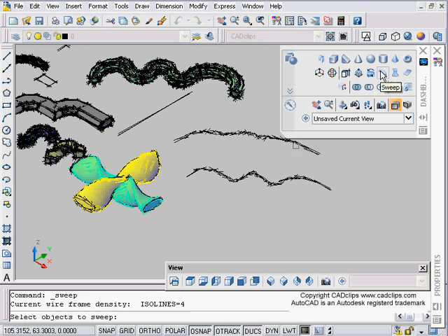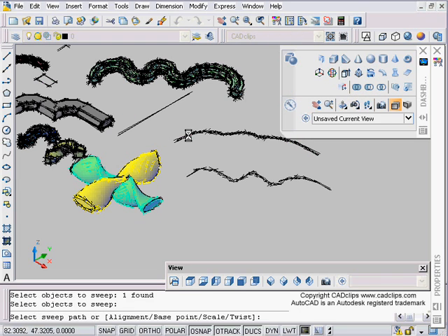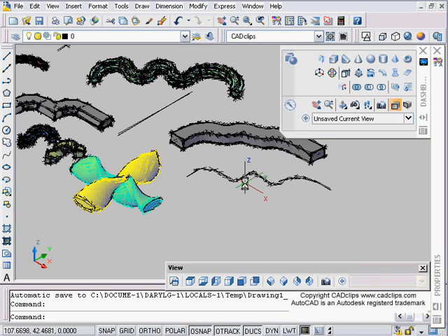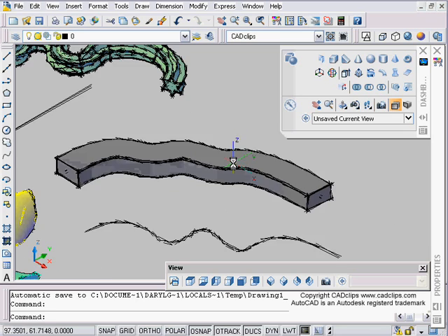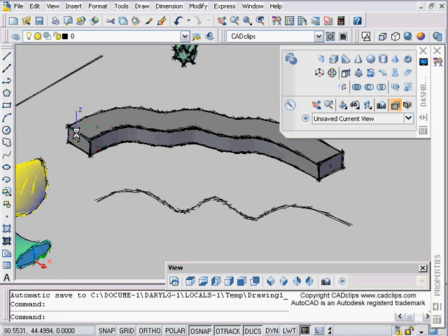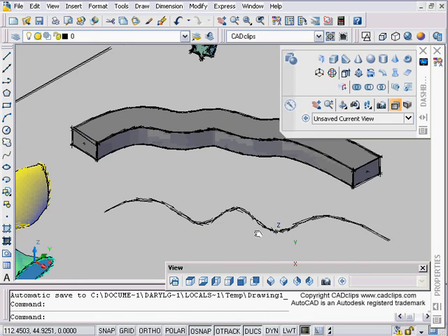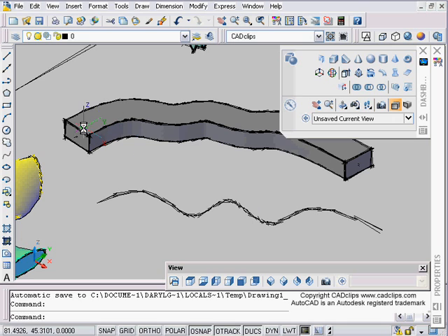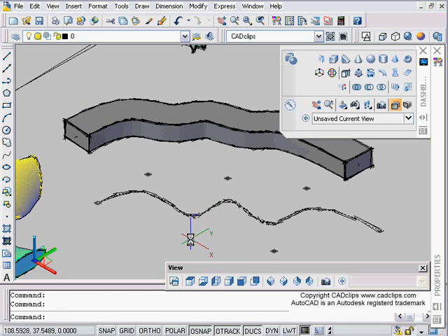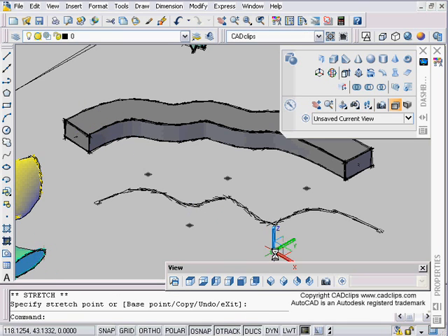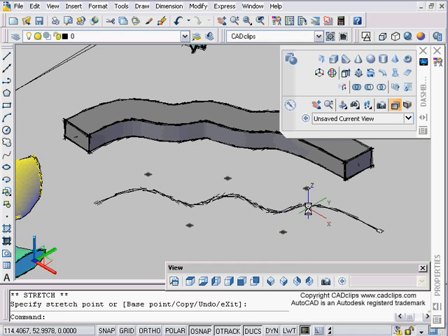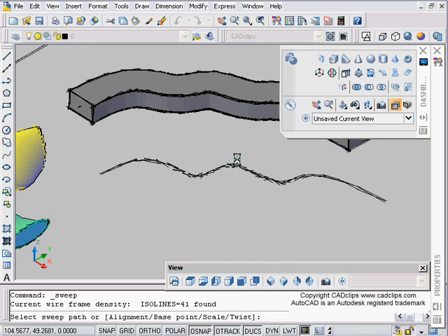Okay, what if we draw just a spline? Let's try this one more time to make sure. This, enter, here. And oh, that time it worked, interestingly enough. So the thing is, you have to be careful if this object is too large and it starts to actually interfere with itself as it goes around the corners. That's where you'll end up with a problem. So that may be the problem with this, is that those curves are a little too drastic.